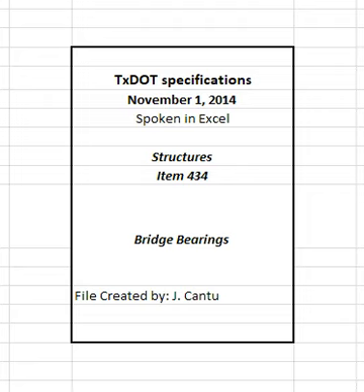Repair of damaged elastomer on top or bottom surfaces of laminated bearings is allowed when approved. Cover edges of steel laminates with 1/8 inches to 1/4 inches of elastomer, except exposure of the laminates will be permitted at approved laminate restraining devices and around holes entirely enclosed in the finished structure. Position laminates within 1/8 inches of plan location.